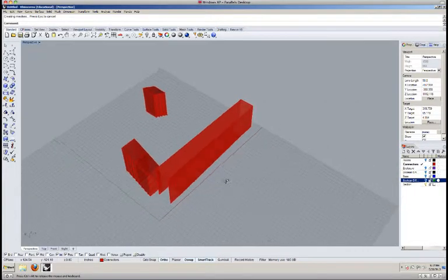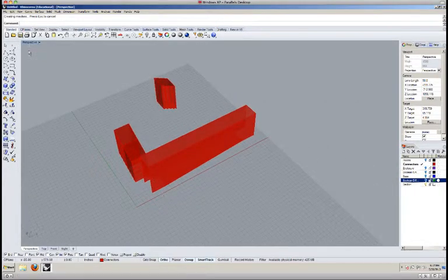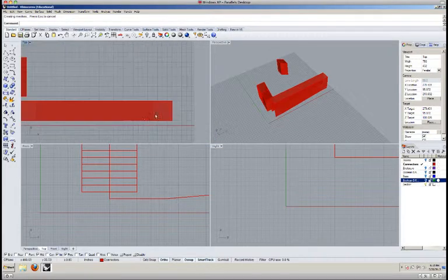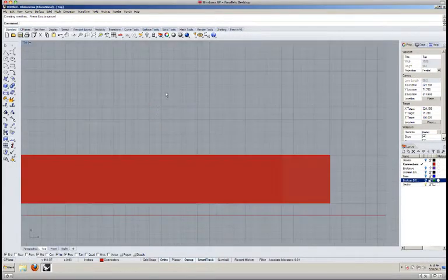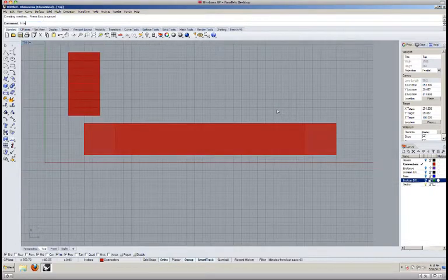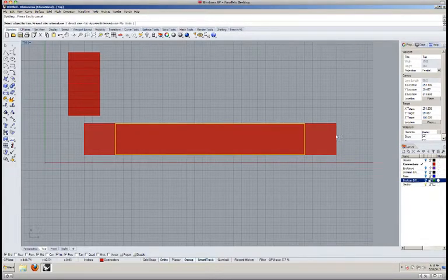One of the reasons I want to do that is because I want to trim off the edges of these. So if I go into the top view with ghosted on, I can use the top of the ramp to be a trim line. So trim, the cutting object is going to be this. I can trim off everything on the outside of it. And I want to turn these to extend lines and apparent intersections onto, yes, and that should let me, now I'll trim.